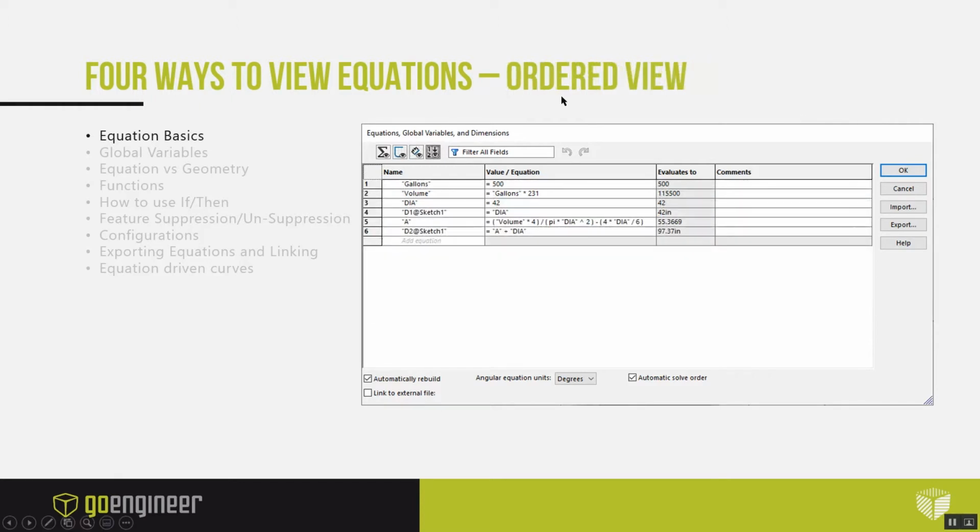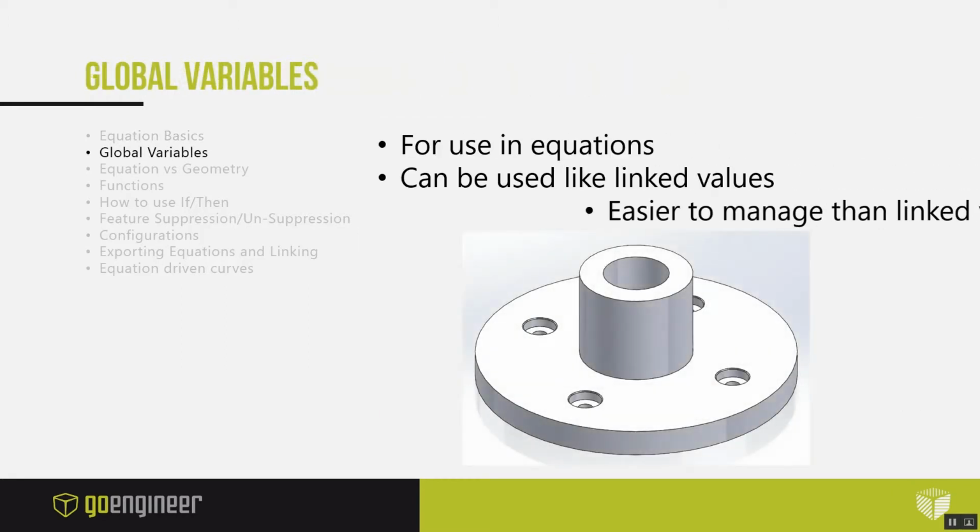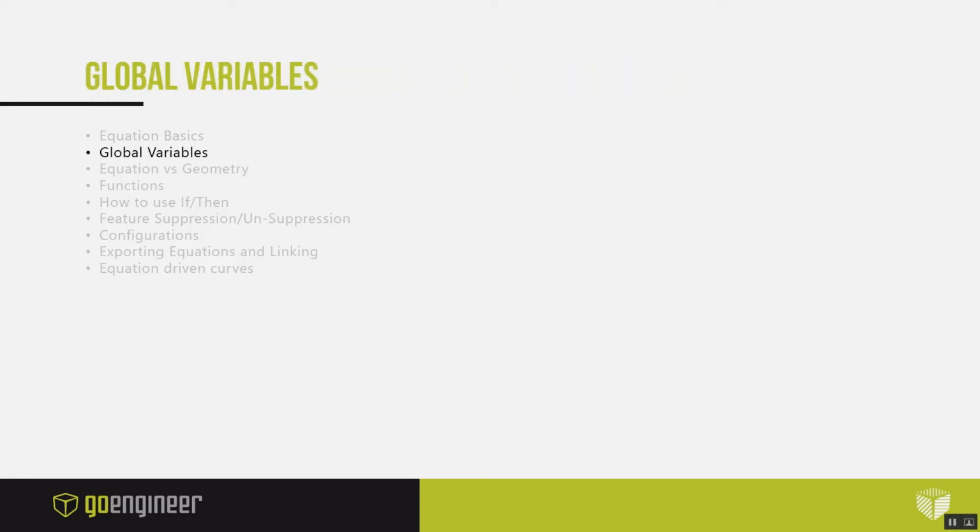And then the last one is an ordered view. Equations in SolidWorks have an order; they have to be in order, from top down. You also can create circular references if you're not careful. So, let's go back now. Let me jump over to SolidWorks.